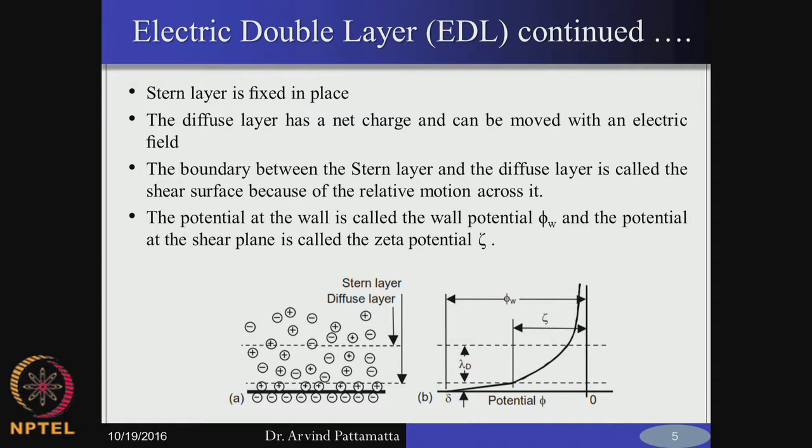So, you have a charge, for example a negative charge, and the base fluid that you have has positive and negative ions. For example, water: H plus and OH minus. The tendency will be for the positive ions to come and settle towards the wall, because the wall is now negatively charged. The first layer of positive charge which accumulates on the wall is called the Stern layer. As you see, this is almost stuck to the wall, so it cannot move. These are positively charged ions stuck to the negatively charged body. The interaction potential is very large, so you cannot simply separate them.